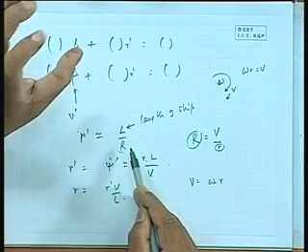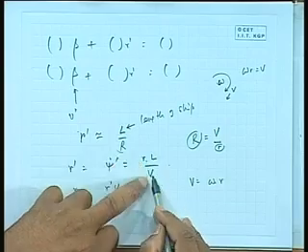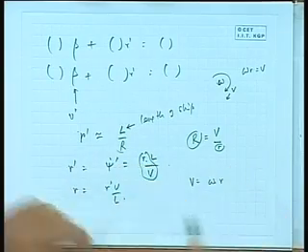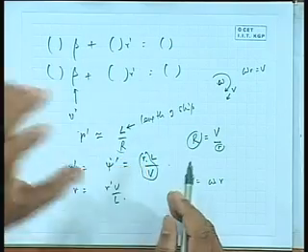Because r dash is the non-dimensional heading yaw velocity, which is rotational velocity into L by V. Tangential velocity and rotational velocity are connected by the radius, so r dash can be related to capital R. Tangential velocity is rotational velocity into the radius, right.